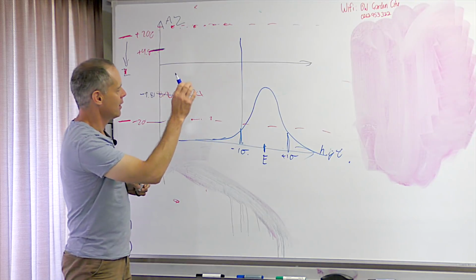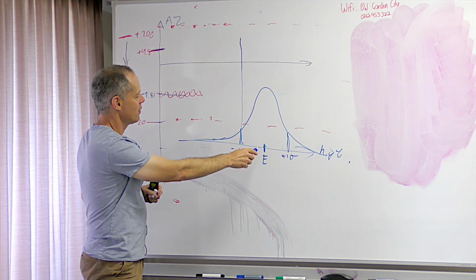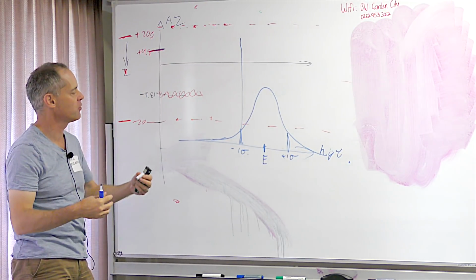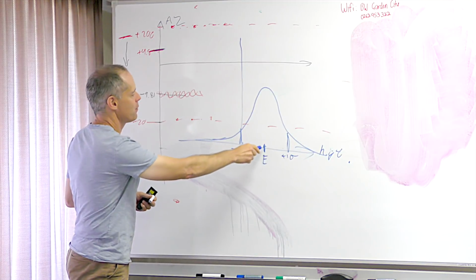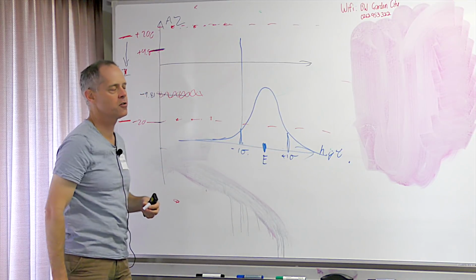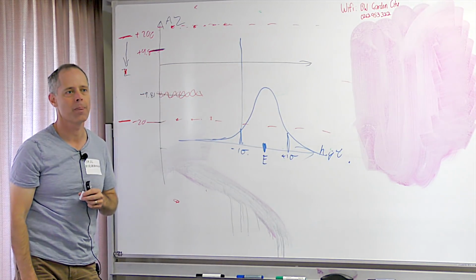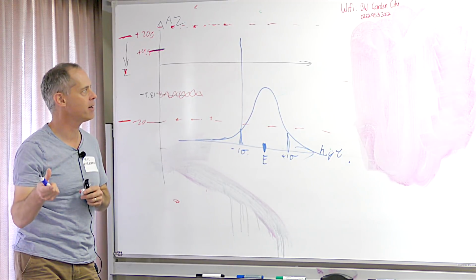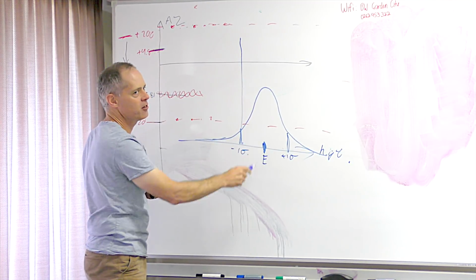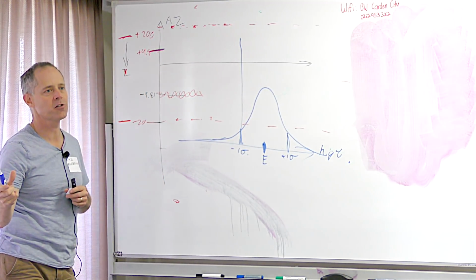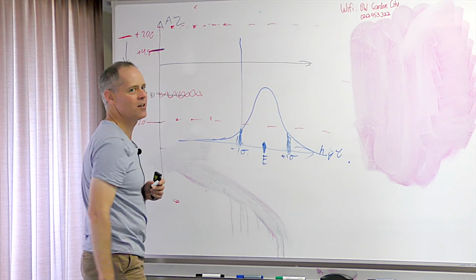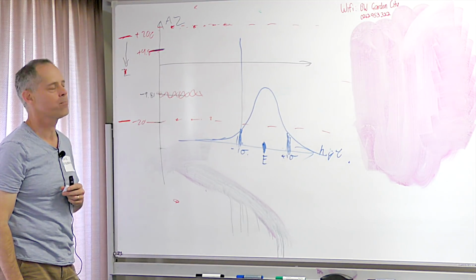The EKF assumes that all the operations used to propagate things forward in time are linear, and it uses that to reduce the number of computations, and it assumes that all the distributions look like that. So what you carry around in the EKF is a state vector, which contains the expected value, and the covariance matrix, which contains the information for each state about what that 1 sigma value, that distribution, is.